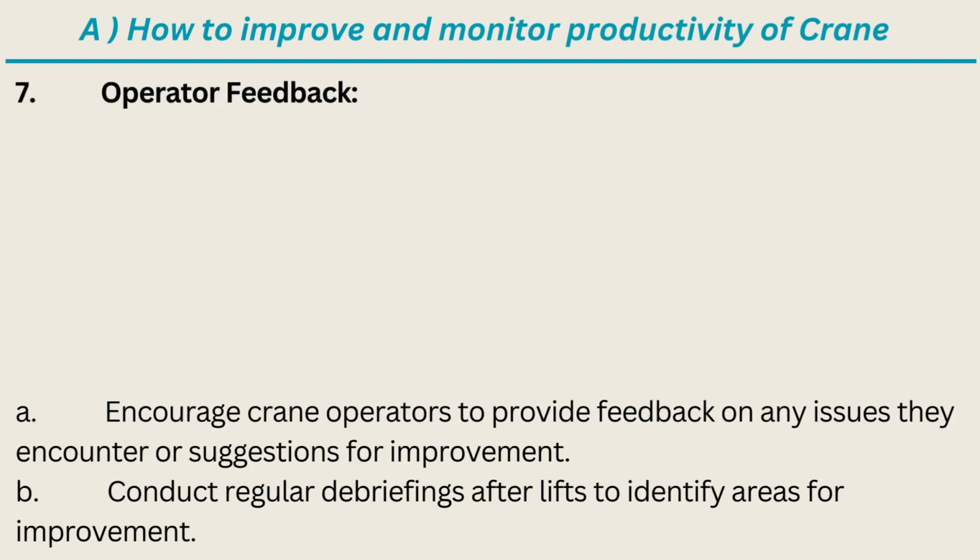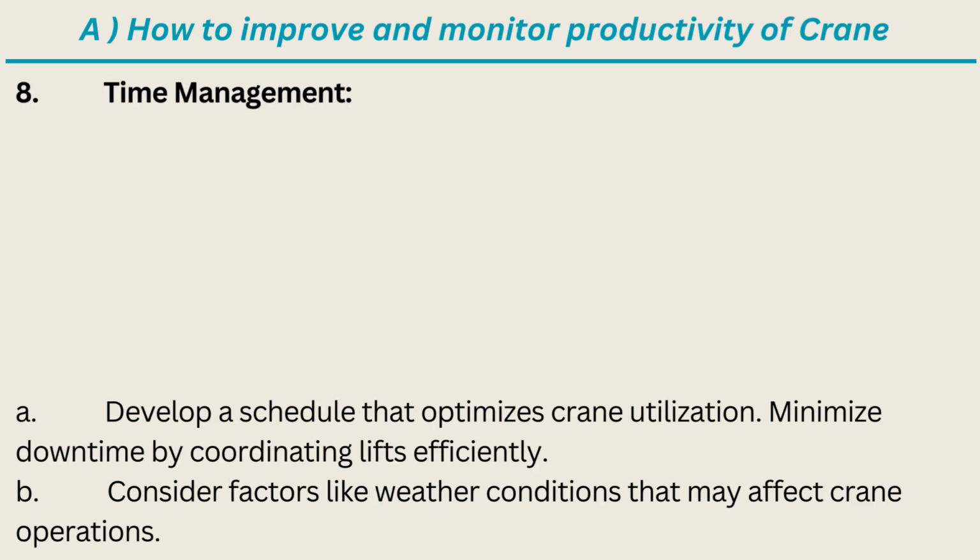devices. 7. Operator feedback. Encourage crane operators to provide feedback on any issues they encounter or suggestions for improvement. Conduct regular debriefings after lifts to identify areas for improvement. 8. Time management. Develop a schedule that optimizes crane utilization. Minimize downtime by coordinating lifts efficiently. Consider factors like weather conditions that may affect crane operations.